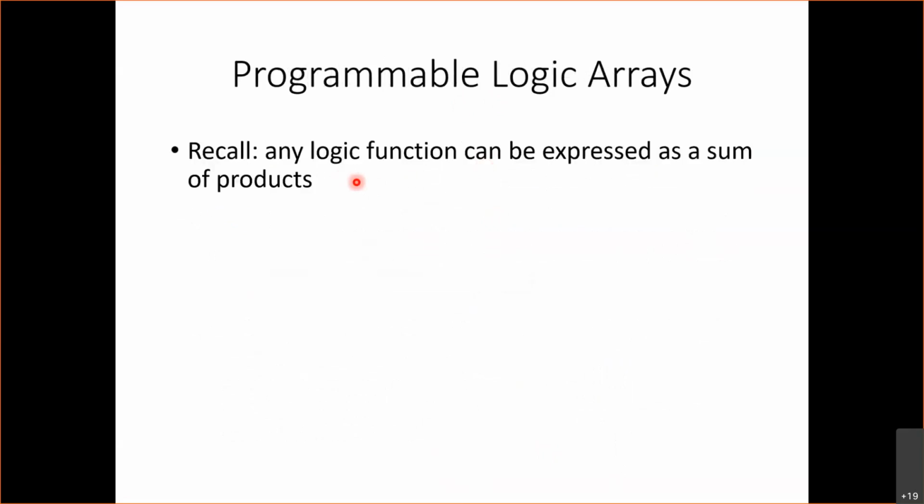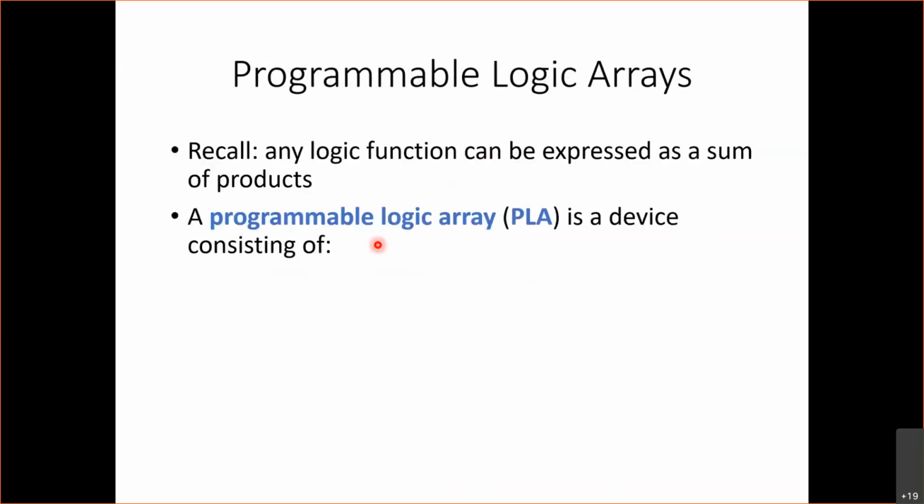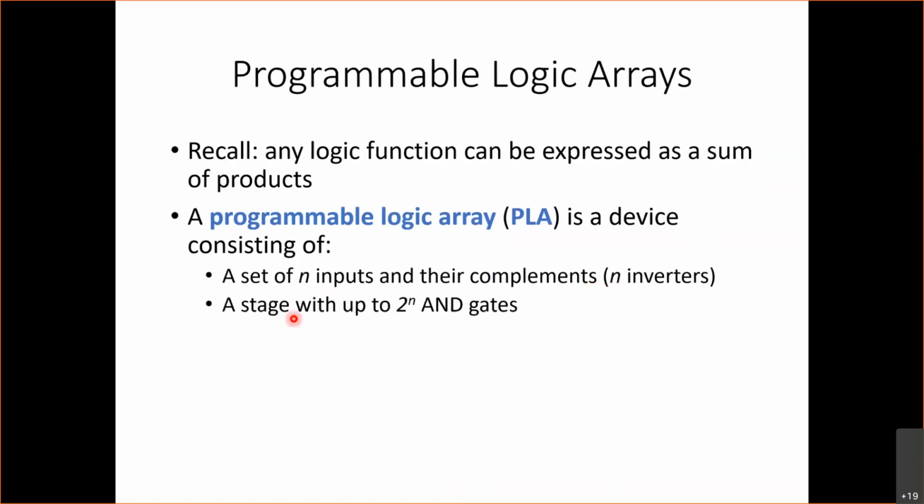A programmable logic array is essentially a device consisting of a set of inputs and all their complements, so we have n inverters. We have a stage with up to 2 to the power n AND gates. And then we have a stage with m OR gates that produce m outputs. So these 2 to the power n AND gates feed into these m OR gates to produce m different outputs.